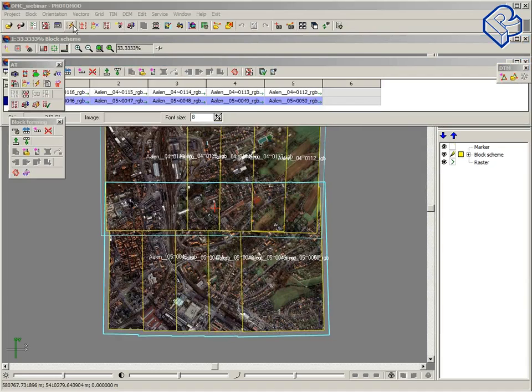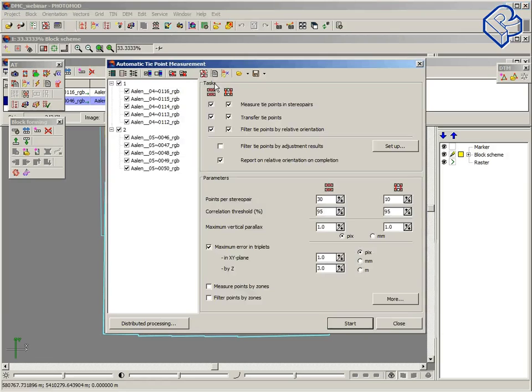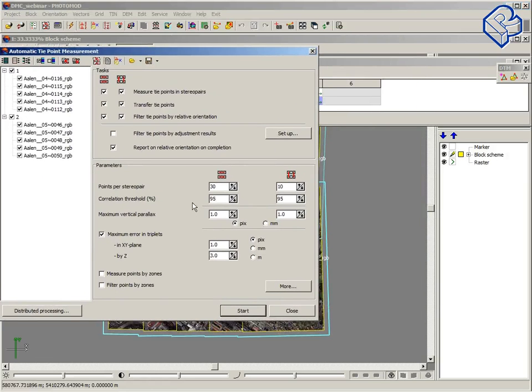Well, the main parameters, as Sasha said, are the acceptable values for correlation. It's about 0.9 or better for good quality images. Vertical parallax is about a pixel in plane. Triplet is about a pixel in plane and depends on the ratio between the focal length and the basis by Z. For digital cameras, usually it is 1 and 3 or 4.